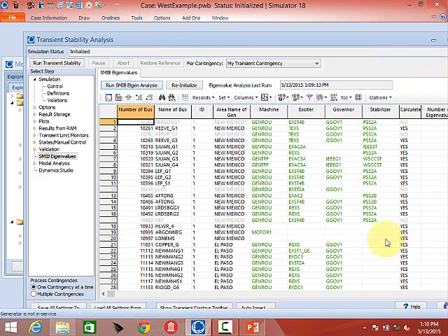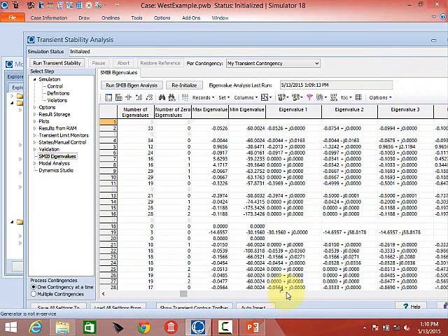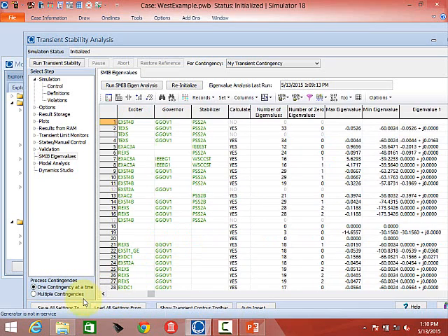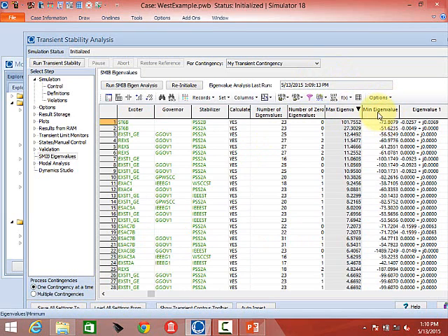The most useful columns here are the max eigenvalue column and the min eigenvalue column. So it calculated all these values. What I tend to do is sort on the max one. And what you'll find is there's a number of them that have positive eigenvalues. We're working on tracking down what the issues associated with these are. I think it has to do with what sort of input comes into the stabilizer. If you bring bus frequency into the stabilizer, there are some issues with that.